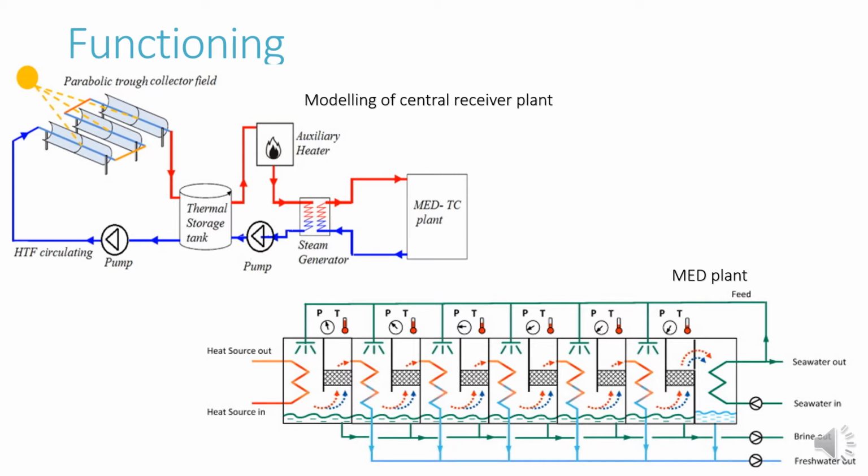The desalination plant uses sprayed horizontal tube bundles for seawater evaporation, which must be limited to around 70 degrees Celsius to avoid scale formation. The MED plant is composed of 14 cells at successively decreasing temperatures and pressures from cell 1 to cell 14. The seawater is preheated from cell to cell in the 13 preheaters. From cell 1, the seawater passes from one cell to another by gravity before being extracted from cell 14 by the brine pump.